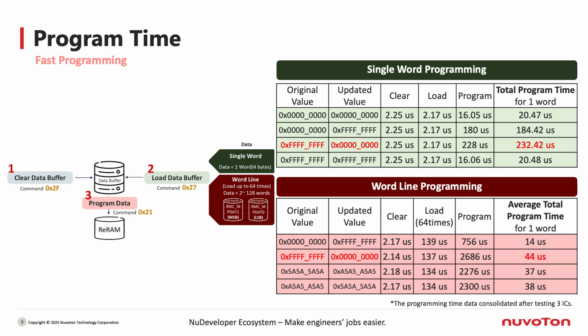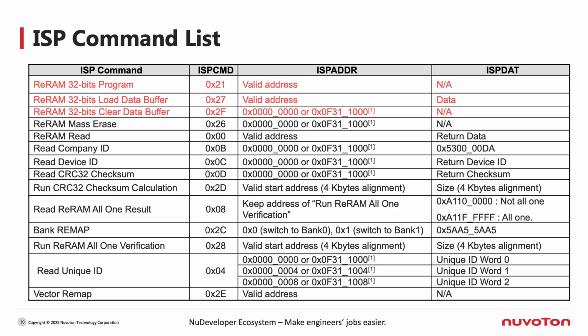Therefore, in real applications, if page-level writing or updating is required, it is recommended to use word-line programming, which can significantly reduce the overall programming time. Here is a list of all the commands used for memory operations.